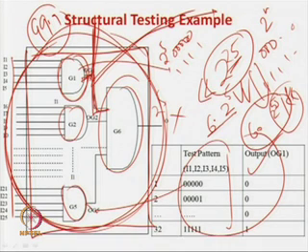Similarly, for this gate also, this gate is directly connected to this AND gate inside, and this is not brought out in the chip. So you can test the circuit, fine, you can easily apply the test patterns, but you cannot observe it directly. So you can bring out the pins. So that is one thing. So for all such nets, you have to bring out pins.